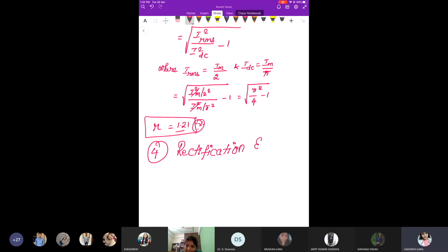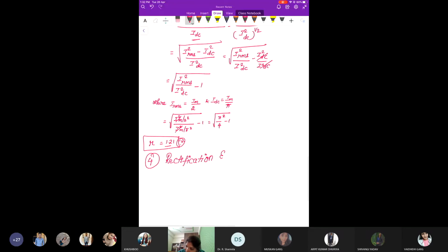Ma'am, input given to the system divided by... So generally the efficiency is nothing but your output by input. Generally, how much output we got for the input. Here we are going to measure the rectification efficiency. In the rectifier the output is DC only, so we measure the efficiency of the rectifier as the output DC power to the input AC power we have given.